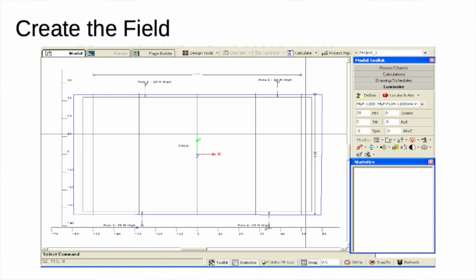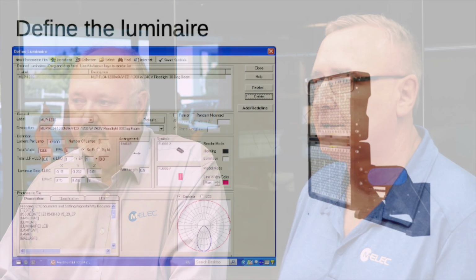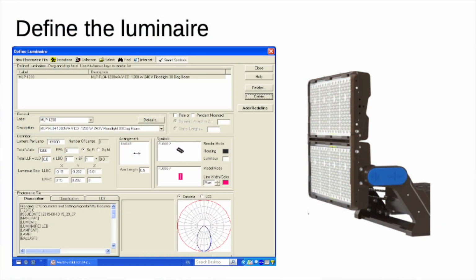and we're getting all the specifications and whatever's required. But what is required? Do I just pick a luminaire and say it's going at this height? So us as designers will pick the appropriate luminaire we feel for the height that we're going to put, if there's existing poles or if there's not existing poles. And then we have to give it the light loss factor, which is the total LLF you see at 0.8 there, which takes into consideration depreciation of the luminaire and the chips.